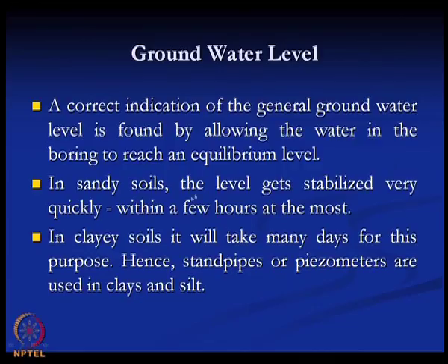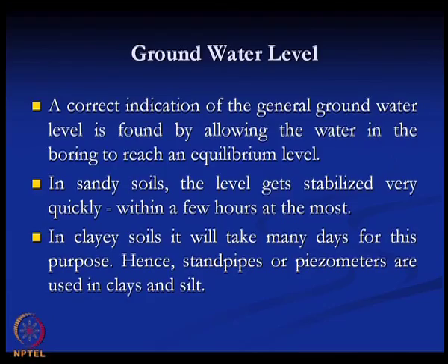Now, if the soil is sandy soil, the level gets stabilized very quickly, within a few hours at most. For sandy soil, the water will reach the equilibrium condition within an hour. But if it is a clay soil, then it may take a day, many days for this purpose. Hence, the standpipe or piezometer are used in clay and sand.